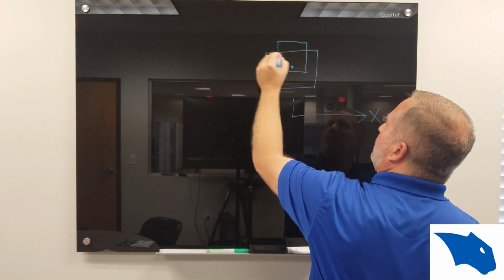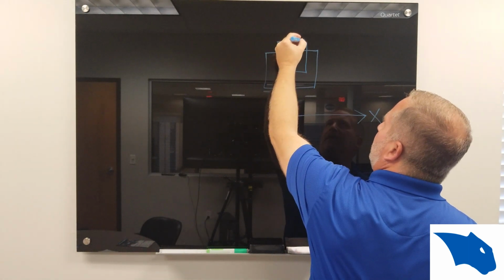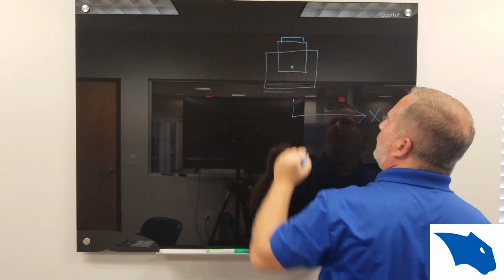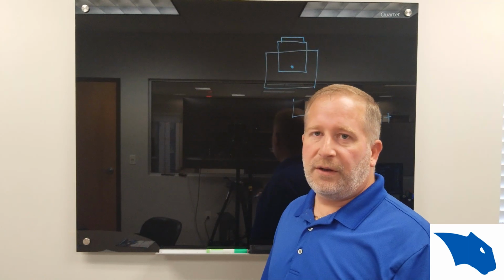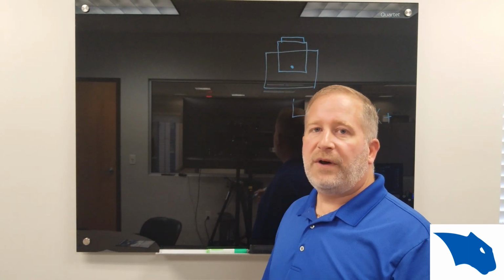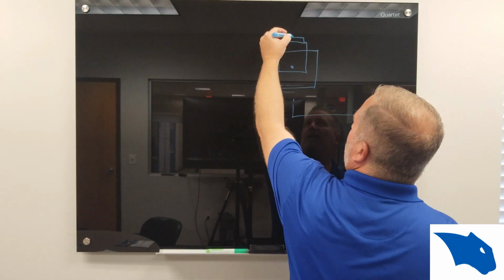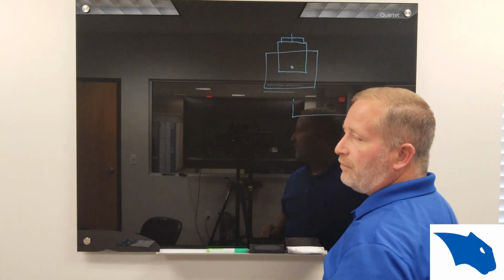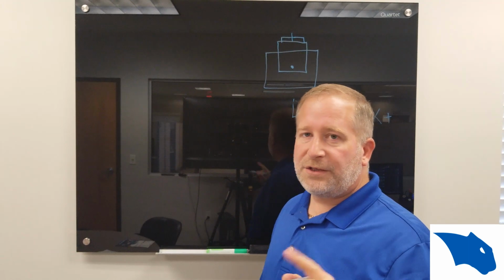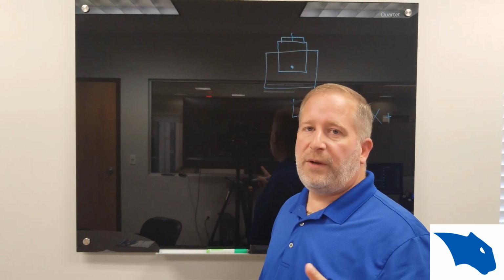We'll call this our center of rotation, and here is our rotary platter. What we want to do in this position is, using a probe or any other measuring method, find the center of the face of the rotary platter. That's the first point. We'll call that point P1.